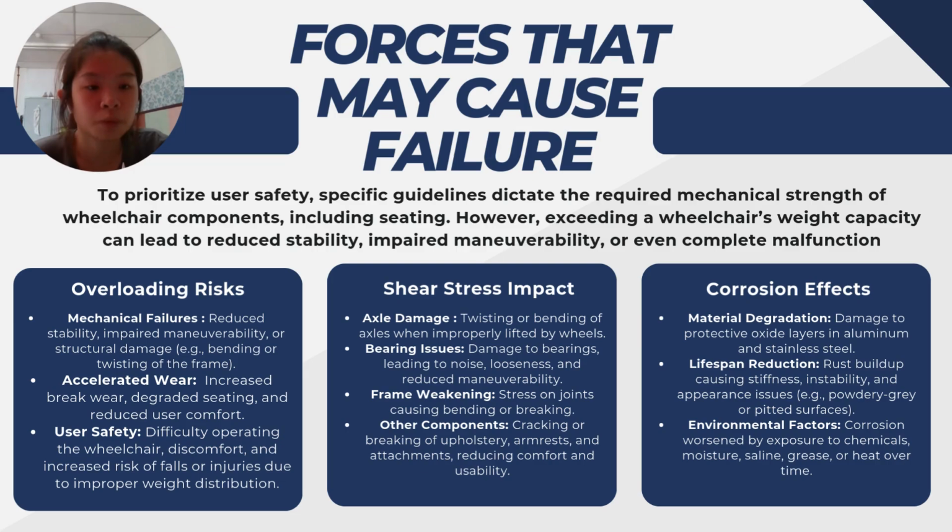First, axle damage. It occurs due to twisting or bending of axles when improperly lifted by wheels. Besides, bearing issue occurs when there is damage to bearings, leading to noise, looseness, and reduced maneuverability. Frame weakening, stress in joints causing bending or breaking, and lastly is the cracking or breaking of upholstery, armrest, and attachment, reducing comfort and usability.